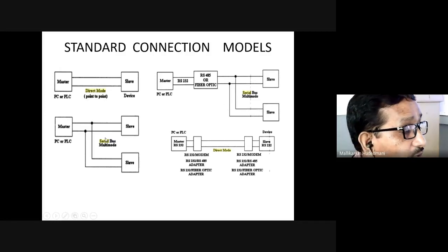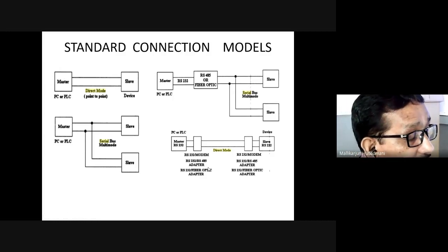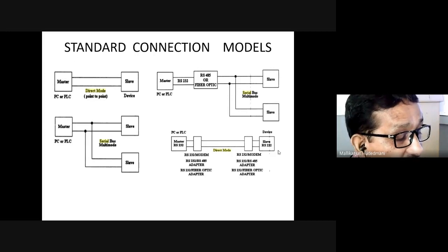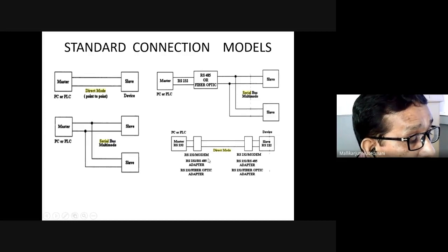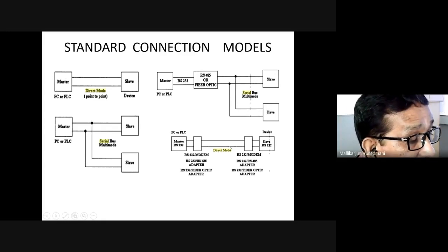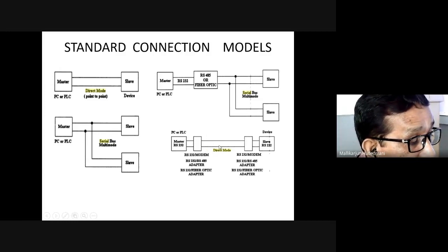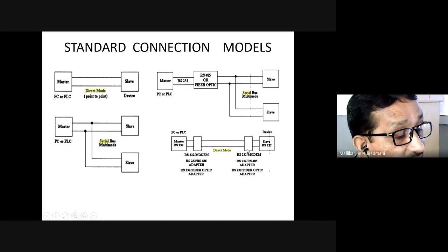A similar diagram was shown in a simplified version. It may be far away, plant to plant. There is a communication station, and far away there is an equipment whose information I want to get connected to. If it is a physical device nearby, I can connect the wire directly. If it is far away, then I should have a master unit, a proper communicating device. We call it a modem, modulator or demodulator, which will communicate and transmit the signal over the public line or service provisions, so that those service provisions have, on the other side, a similar mechanism interfacing to the device.